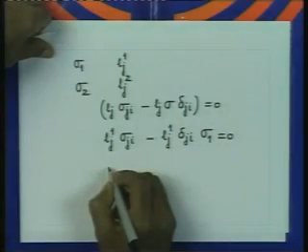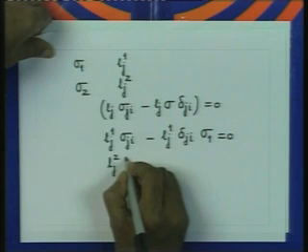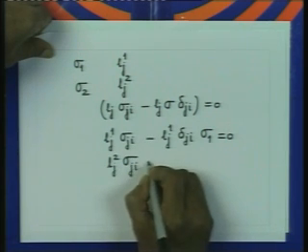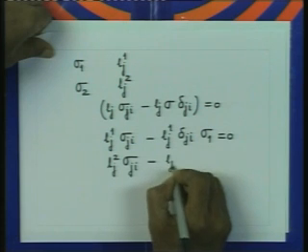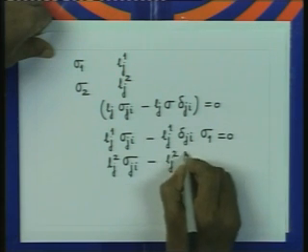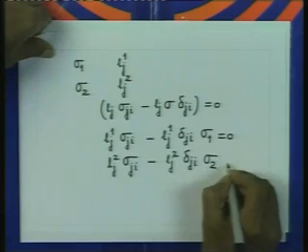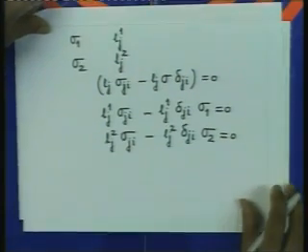So, this is the set we get from the principal stress sigma 1. Similarly, for the principal stress sigma 2, without any difficulty you can write Lj2 sigma ji minus Lj2 delta ji sigma 2 equal to 0.